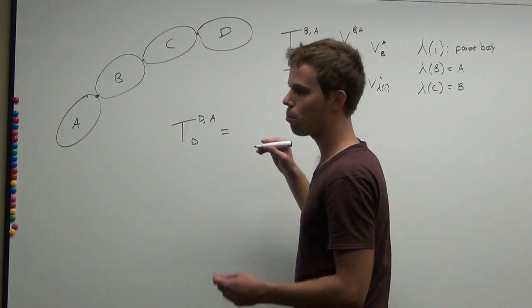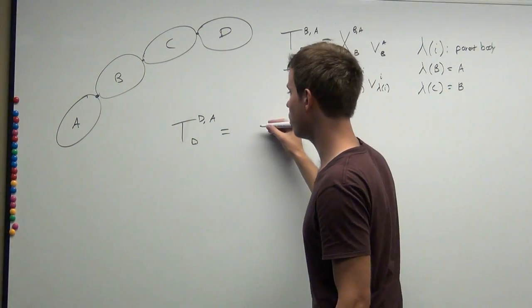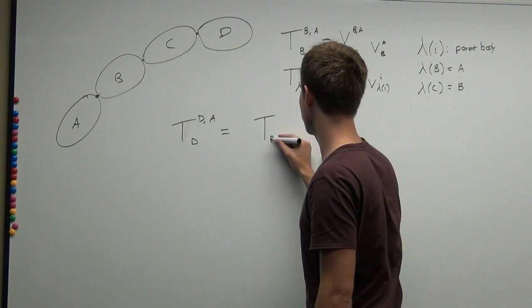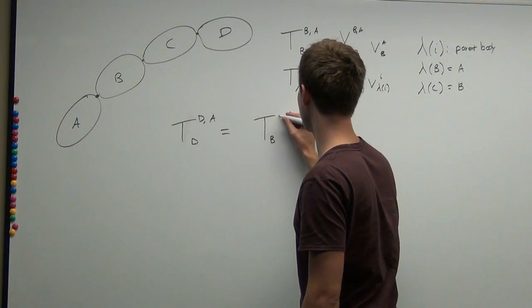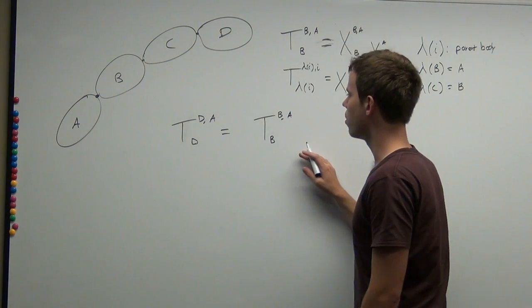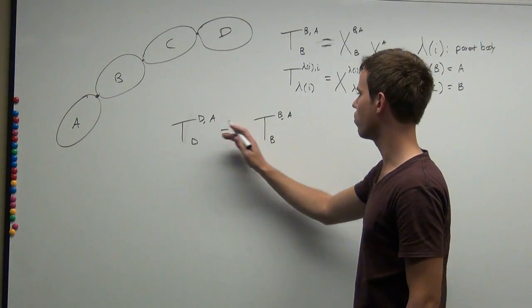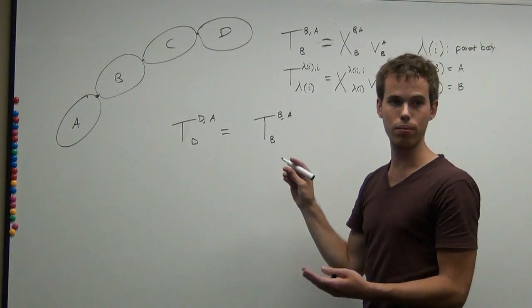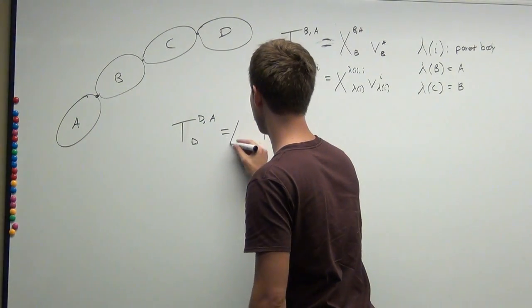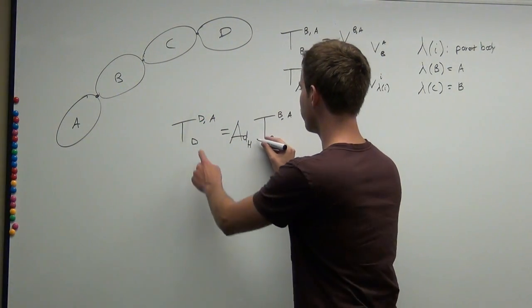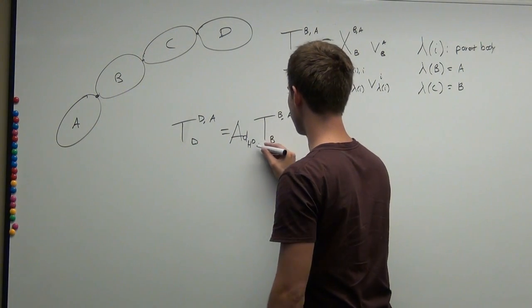So we probably know the twists locally. So we have T of B with respect to A expressed in frame B. But then we want it in frame D. So we're going to add everything up in frame D. So we'll have to pre-multiply this joint matrix, change frames, H to D from B,